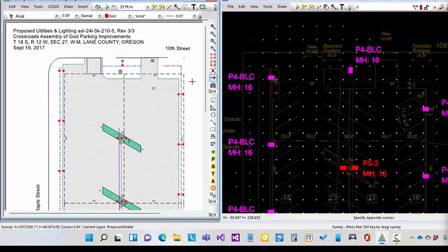Now, that's great. This happens to be a lighting plan from Hubble Lighting at 0, 0, but how often do I get plans from an architect at quarter scale, 4 feet to the inch? Or how often am I working with my survey at state plane projection, and I get a CAD file for the project at ground elevation? So now I've got to reconcile grid to ground. So the reconciliation, the calibration can be large, as it is in this extent, or it could be pretty small. Sometimes that grid to ground stuff isn't that big necessarily, but we have to account for it. So let me show you how we do this.